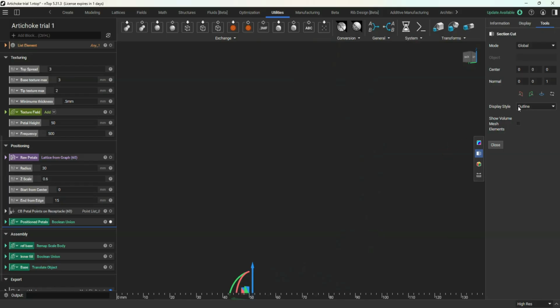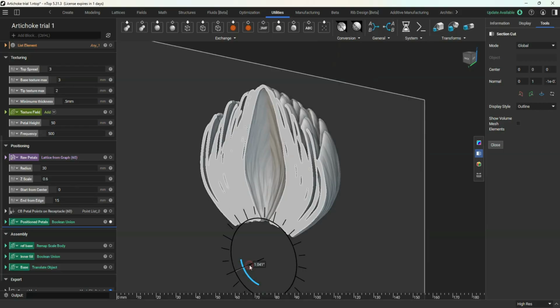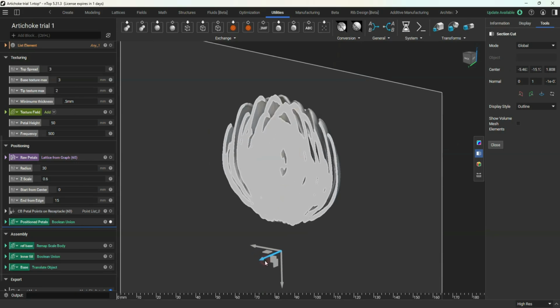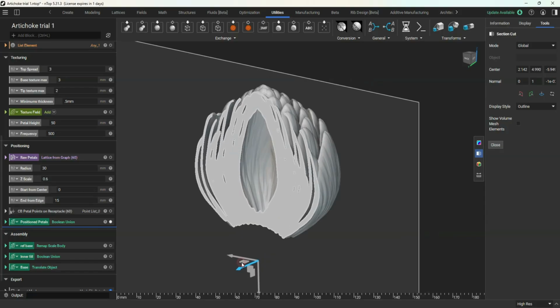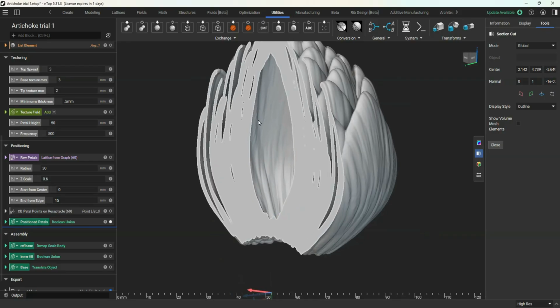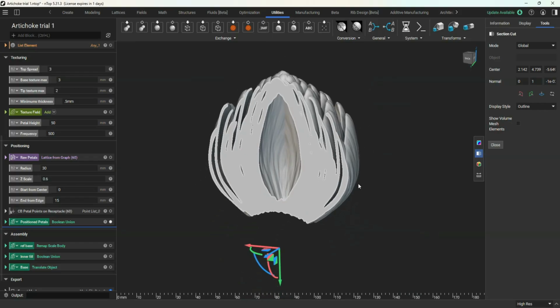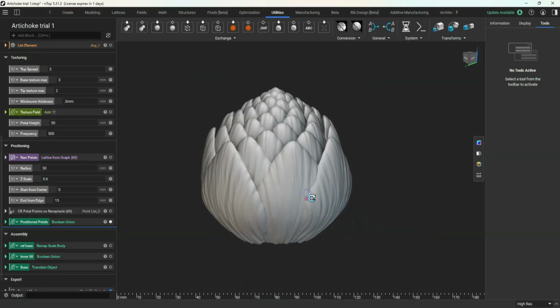If you look at the cross section of it, you can see that there's a lot of hidden internal geometry there that is first of all, it's not going to be seen, and it just complicates the model. So in the final, when I'm preparing this to print FDM, I'll show you in a minute. I just take out a lot of that internal geometry and just leave only what's visible on the outside there.